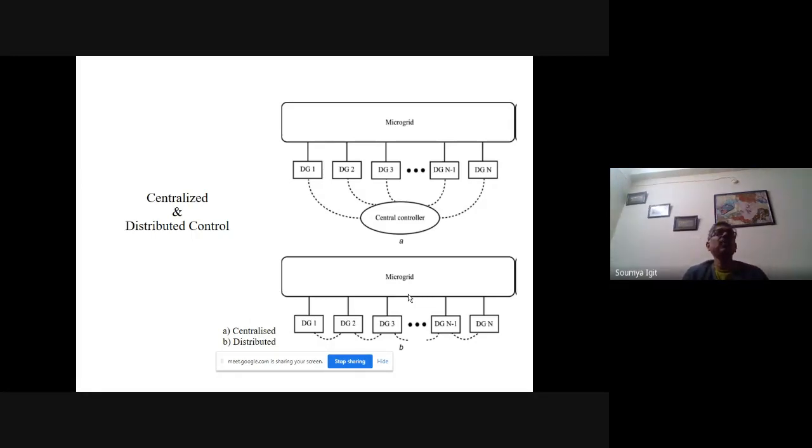And sometimes when you talk about robust control, the control effort has a computational burden, so make it event triggered. That means at the time when the inclusion of the uncertainty in the system is remarkable, let it be event driven. Otherwise, let the controller act accordingly.